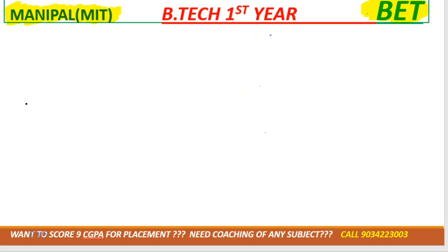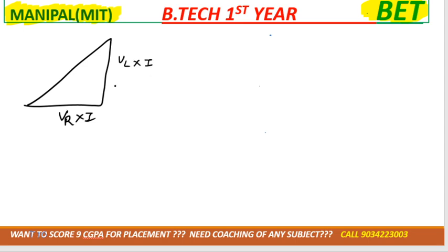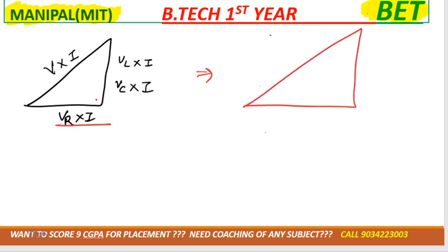Now suppose I multiply voltage with the current, so what will it become? Tell me. Power, exactly. So after multiplying it we'll get the power. Here is the resistor, so for the resistor, as I just told you, we will have active power, and active power is denoted by P. In the case of inductor and capacitor, we will have reactive power. Reactive power is denoted by Q, and total power is the apparent power.